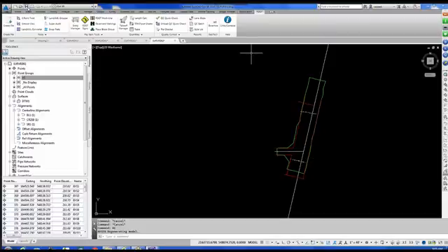So in this file, my ServRD file, I had a surface that came in directly from the CAiCE database. I brought in all these points from the CAiCE database. I then manipulated the points by creating new point groups manually because I didn't run them through a grouper, so it didn't create those groups for me automatically. And then it brought in the realignments. All right. Let me get back to my desktop here.